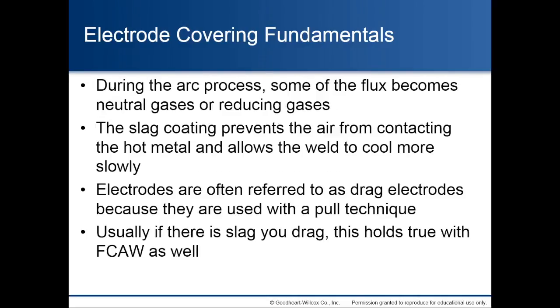Electrode covering fundamentals. During the arc process, some of the flux becomes neutral gases or reducing gases. The slag coating prevents the air from contacting the hot metal and allows the weld to cool more slowly.